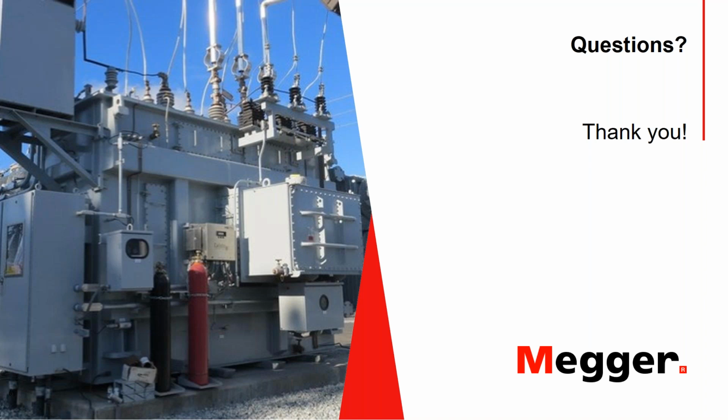I'll give you an example. Let's say you see an instrument whose capability is 100 amps. Also look at the compliance voltage of the instrument, as it is equally important as the current to achieve stable readings as fast as possible. In other words, an instrument with 100 amps capability but a low compliance voltage won't be of much help compared to an instrument with 50 amps but a higher compliance voltage. So yes, the voltage is defined by the instrument, but look at the specs. This is important when selecting an instrument to perform these measurements.